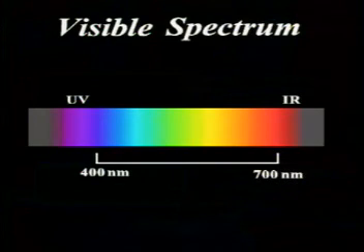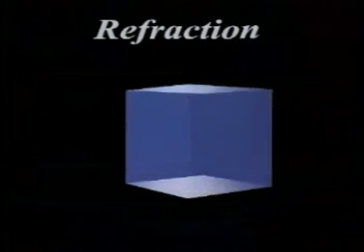Optical wavelengths are measured in nanometers, or billionths of a meter. Blue light has wavelengths of around 400 nanometers, while red light is approximately 700 nanometers. The infrared area starts around 800 and increases to about 100,000 nanometers as it approaches the microwave region. It is the infrared area we are interested in for most fiber optic applications.